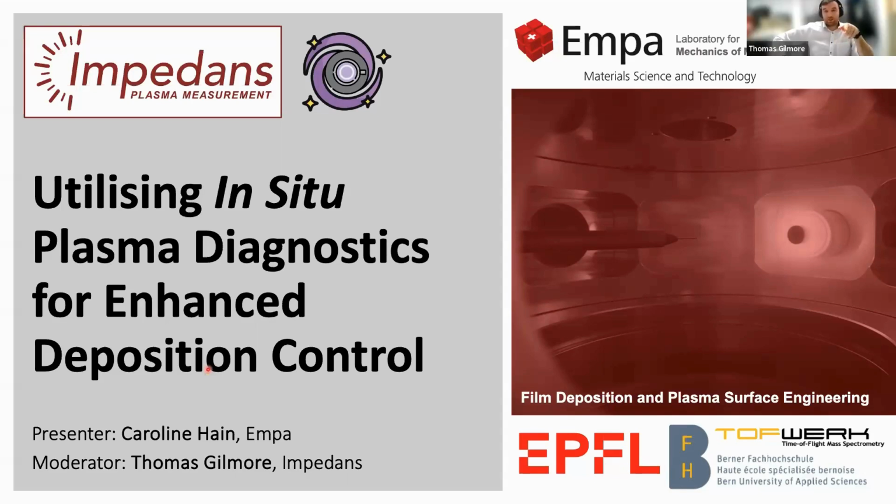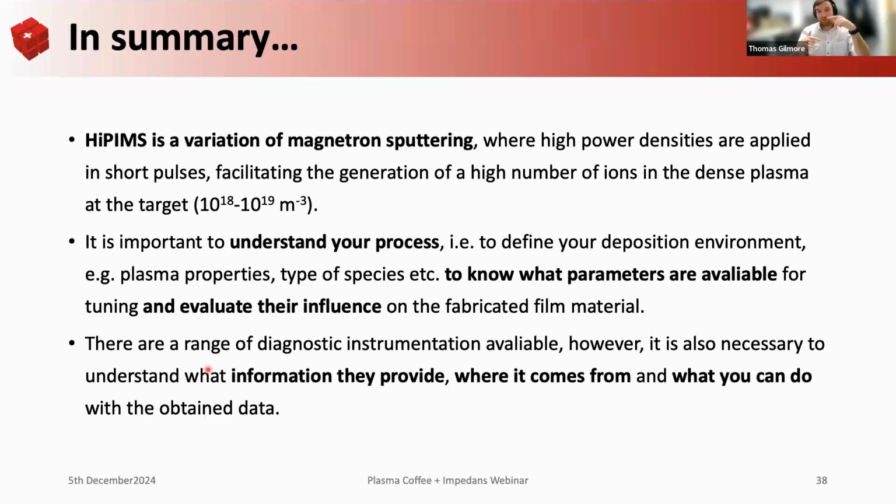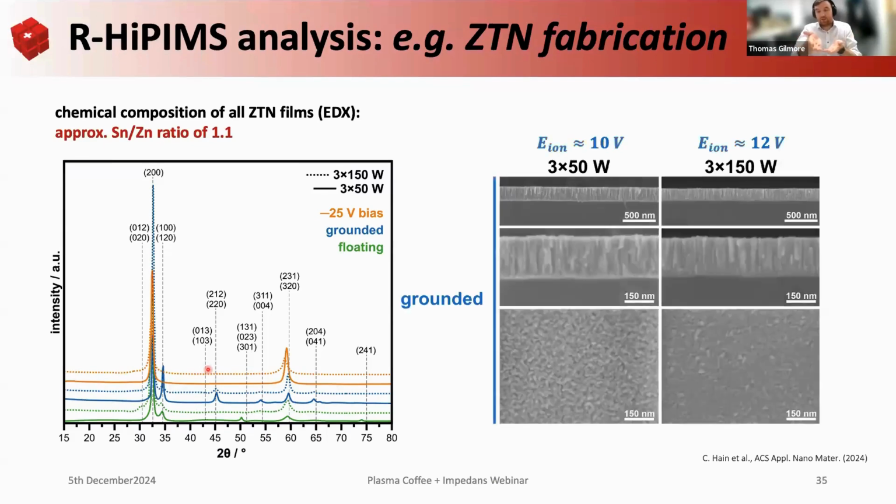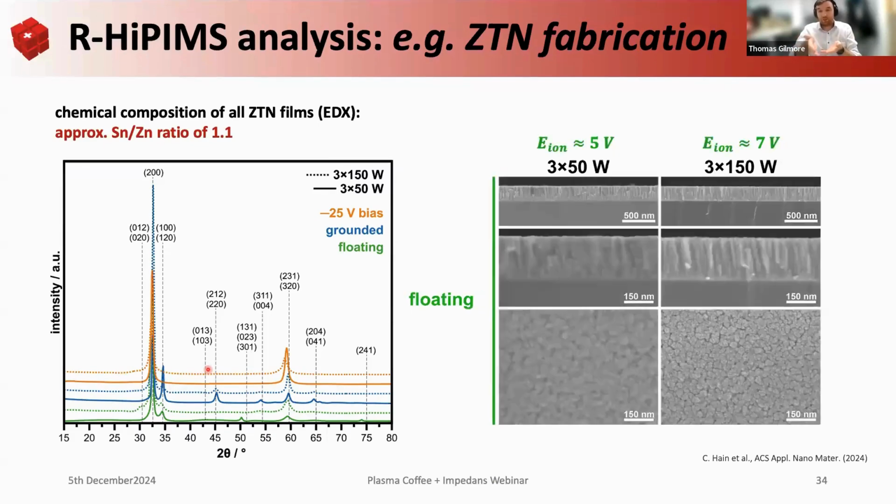Like you were showing at the end, even a fairly small change in ion energy, going from floating to grounded and then grounded to a small bias, already changes the material properties, because at these low energies you reach that etching threshold, right? Yeah, so you get some different things. Also, if you multiply the ion flux by the ion energy, it's like the power being deposited.